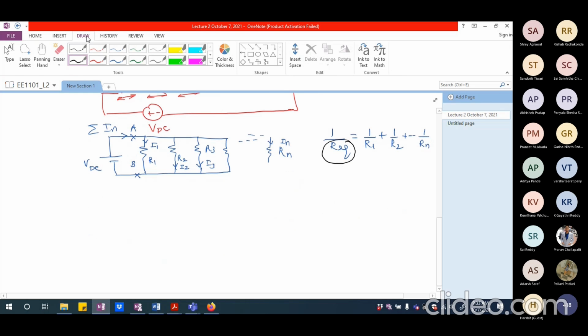Now, when we make electrical connections at home, what we get is a 230 volts, 50 hertz supply. That is an AC supply. And generally we connect all the equipment in parallel, because a lamp is normally rated for 230 volts. If I have to connect, let us say, a motor, which may be a mixer or grinder, then I have to connect that motor right across 230 volts. So all of them are generally connected in parallel.